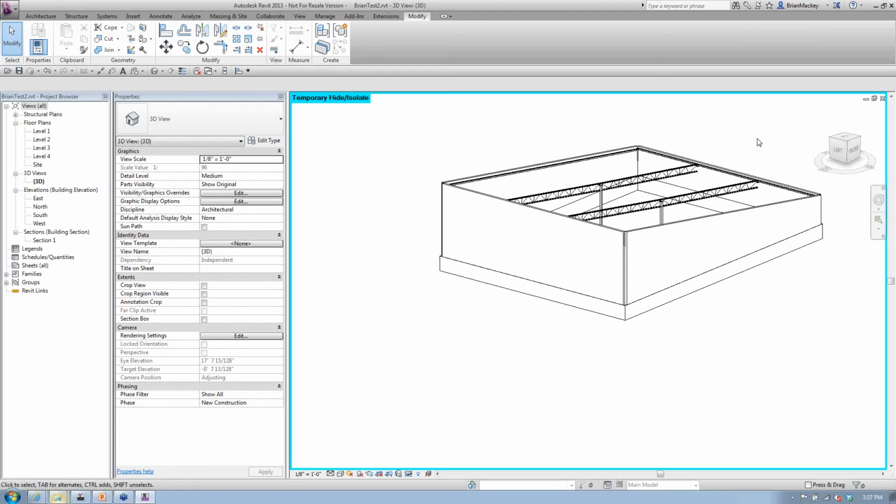I also know the Revit Wiki helped retweeted somebody who had to do a handrail on a little pedestrian bridge, and it had this big, huge arc going into it, and they wanted the handrail to follow the arc. So they created an adaptive component, made sure everything was vertical, and did a handrail. Looked like a handrail at the very least for going up over an arc. So there's a lot of different ways to start using the flexibility of adaptive components. It's really where can you think.